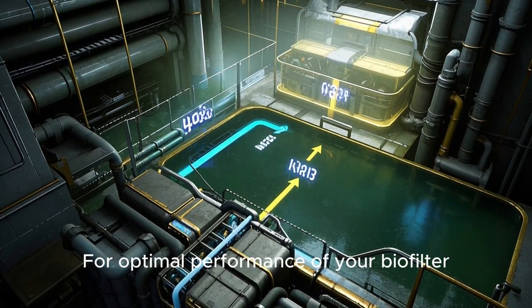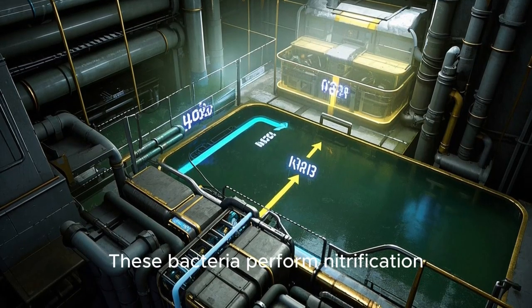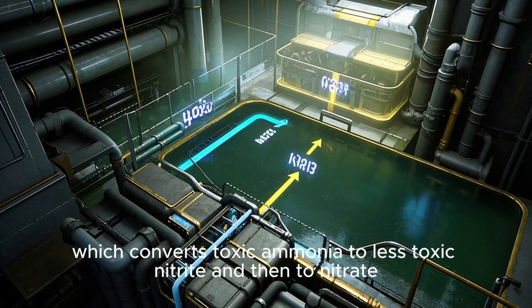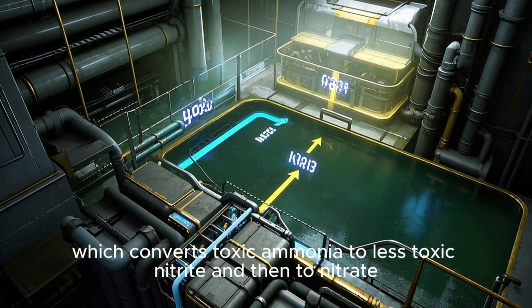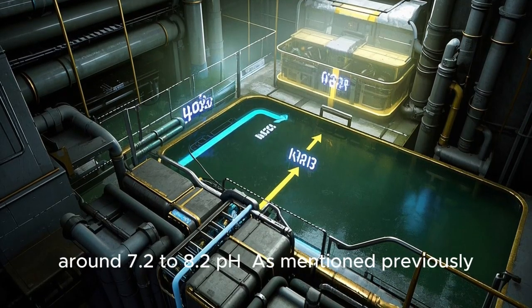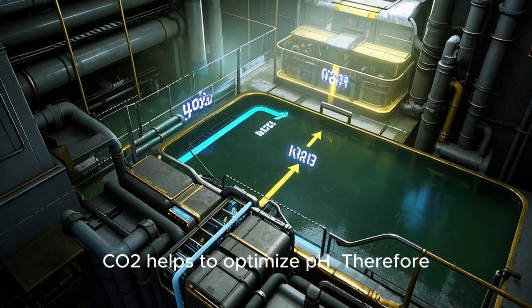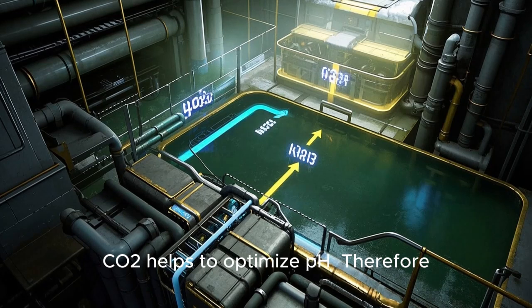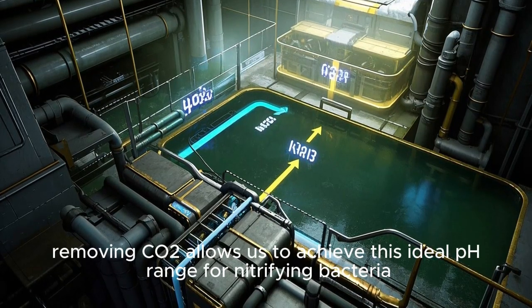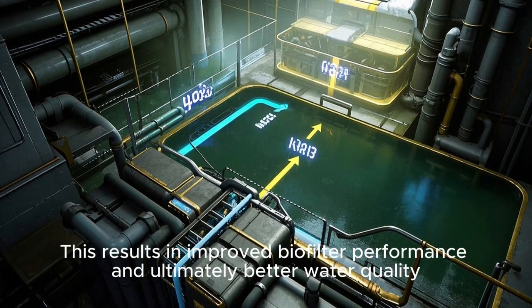For optimal performance of your biofilter, we need to maintain a good balance of bacteria. These bacteria perform nitrification, which converts toxic ammonia to less toxic nitrite and then to nitrate. The bacteria that perform nitrification prefer a more neutral pH range, around 7.2 to 8.2 pH. As mentioned previously, CO2 helps to optimize pH. Therefore, removing CO2 allows us to achieve this ideal pH range for nitrifying bacteria. This results in improved biofilter performance and ultimately better water quality.